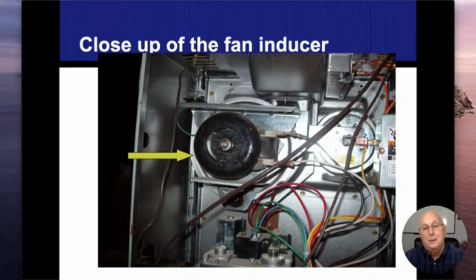All right. Now the computer doesn't know if the wheel is actually creating a draft or working at all, or the wires are broken, or could be, I've seen birds stuck in these things and they didn't operate either. So if it's working and it's going to be creating differences in pressures, we're actually going to sense for that. So this cylinder device right here is called a pressure differential switch. Now sometimes you will see a tube, either it'll go to the heat exchanger or it'll go to the underside of the inducer fan. And if it's spinning, if it's creating those pressures, then that device will close, sending a signal to the computer saying, yep, my inducer fan is running, it's spinning, I created a draft, you're good to go to the next stages. All right.